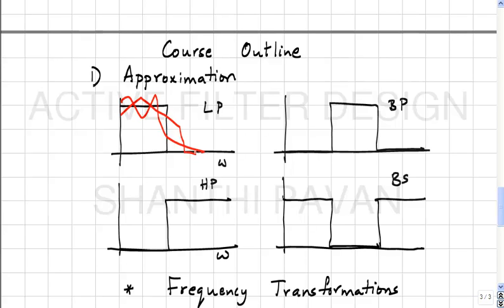One example of two things being close together is in the mean square sense. You find the difference between the ideal and the actual, square the error, and integrate from 0 to infinity, and that gives you one measure of the difference between the two. Another person may say, that doesn't make sense to me. What makes sense to me is the absolute error between the desired and the actual, and not just that, the maximum value of the absolute error. I'm going to work out the math to keep that absolute error to a minimum. That need not necessarily leave me with a solution whose error is small in the least square sense. So all that I'm trying to point out is that there are many ways of doing this,